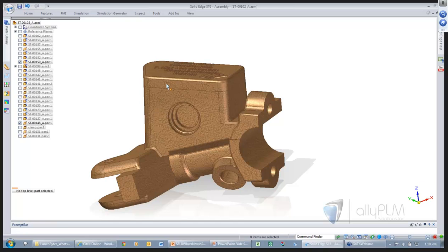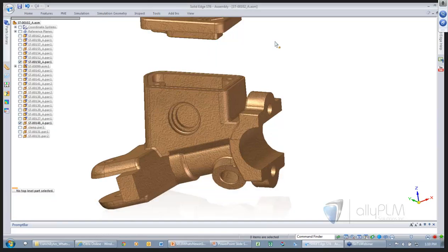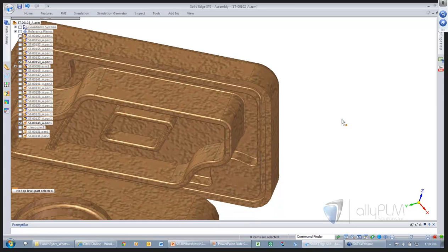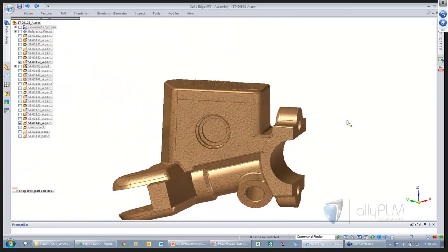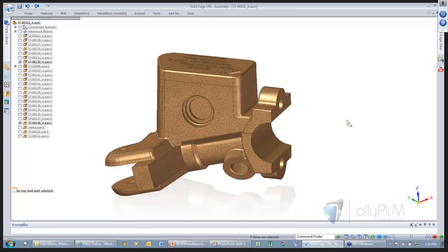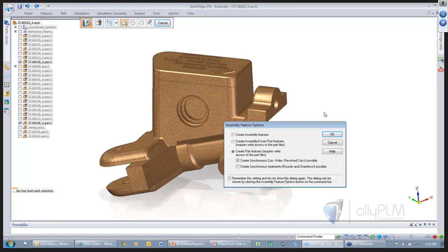So if I go ahead and offset this guy once again, you'll see now there's the female side, that groove in there. I didn't have to go build any construction faces. Just said union, where it sits, subtract this from this, tool from target. Very, very handy. The next thing I want to do is go ahead and place a hole.